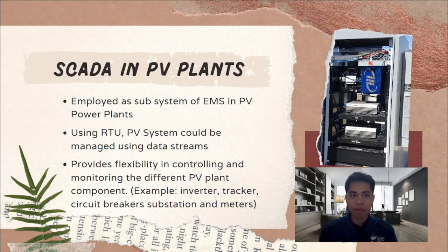SCADA in this PV power plant is employed as a subsystem of the EMS, or what you can call the energy management system, in a PV power plant. Using a remote terminal unit or RTU, the PV system could be managed using data streams. Data streams with a few thousand measurements per second may be used to control the PV system.